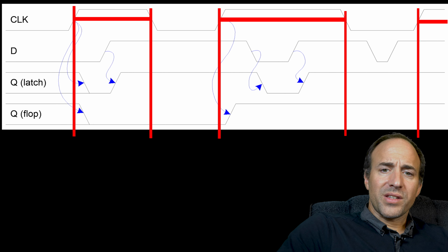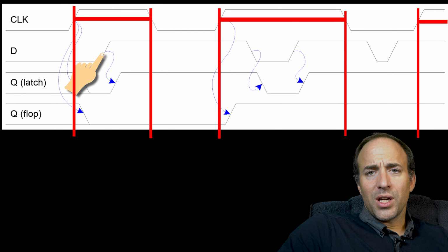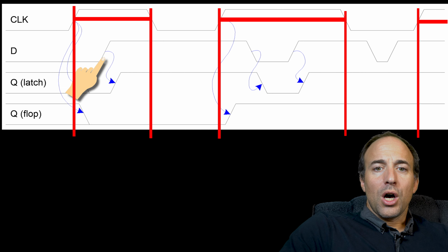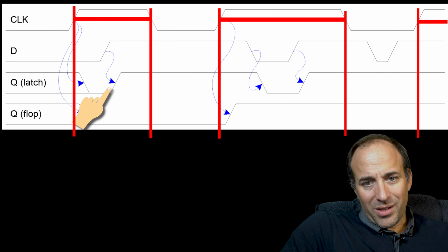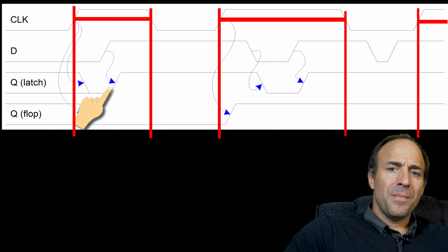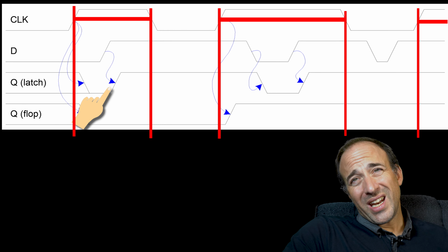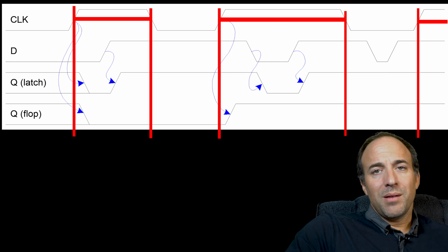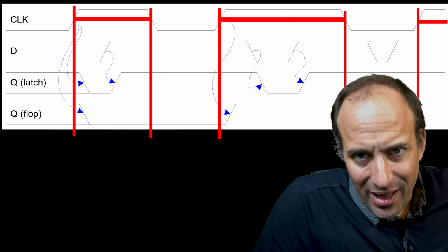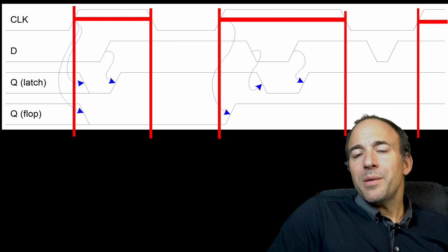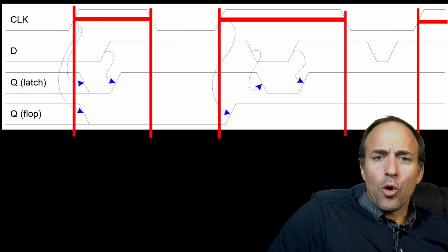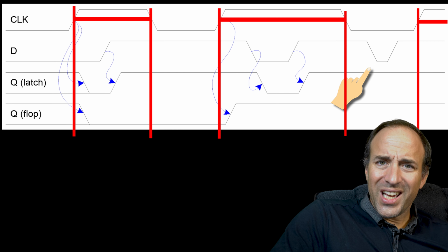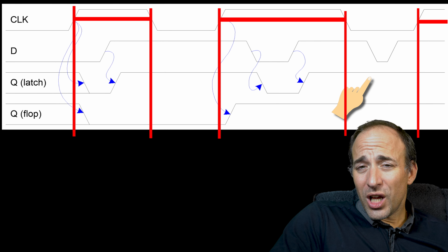A latch acts like a combinational logic circuit when the clock is at a certain level, such as high. In other words, when the clock is high, the circuit's output is a function of its inputs, and the output will change immediately, or rather after the internal combinational delay of the circuit, in response to any input change. So stated another way, when the clock is high, the outputs respond to inputs right away. They respond asynchronously. They're independent of a clock. But when the clock is low, the circuit's outputs are frozen, maintaining their state from when the clock was last high.